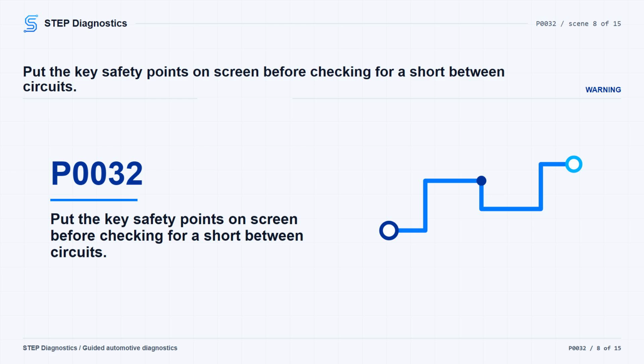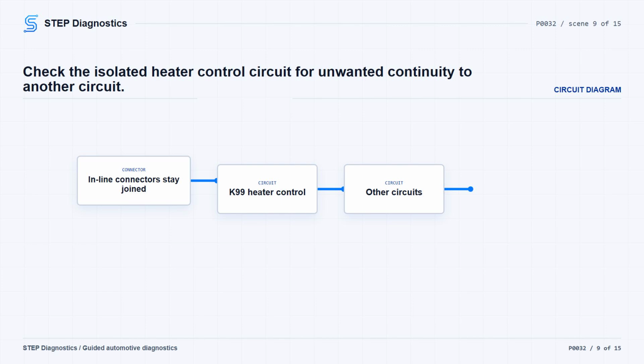Disconnect the ECU and every component connector that contains the circuit being tested, and leave the inline connectors connected at this point. Use the wiring path to follow the circuit. Connect one DVOM lead to the circuit at the ECU harness connector, then probe the other circuits at that connector with the other lead. Do not probe PCM harness connector terminals directly. If a PCM terminal must be accessed, use the GPEC Diagnostic 10436 adapter.